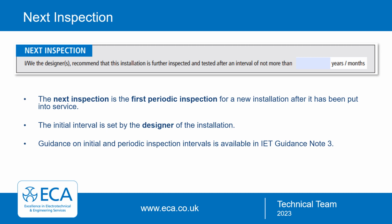As this is initial verification, so this will be the very first periodic inspection for a new installation once it's put into service, the initial interval is set by the designer of the installation, so they will set when the first periodic inspection or EICR is due. Guidance on this is available from the IET in Guidance Note 3.